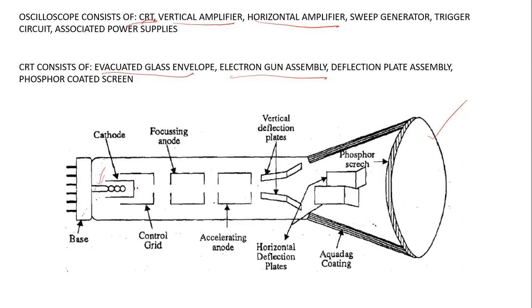In this thermionic emission process, instead of giving energy to the cathode surface via high energy photons, you are giving energy to the cathode surface through heating. When you heat this cathode using the heating filament sufficiently to a high temperature, the energy supplied to the cathode would then be greater than what is called your work function.